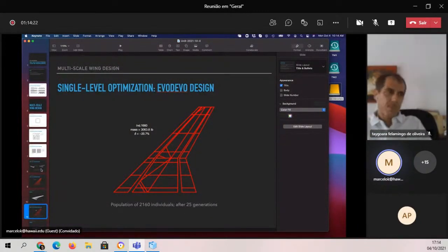It's called the flutter phenomenon, and it is a terrible instability for the wing. The way you model it is you have a reduced model of the dynamics of the wing using modes of the wing. In that case, we calculate the eigenmodes, and then we reduce the dynamics using those eigenmodes, and we solve the stability issue in that reduced model.